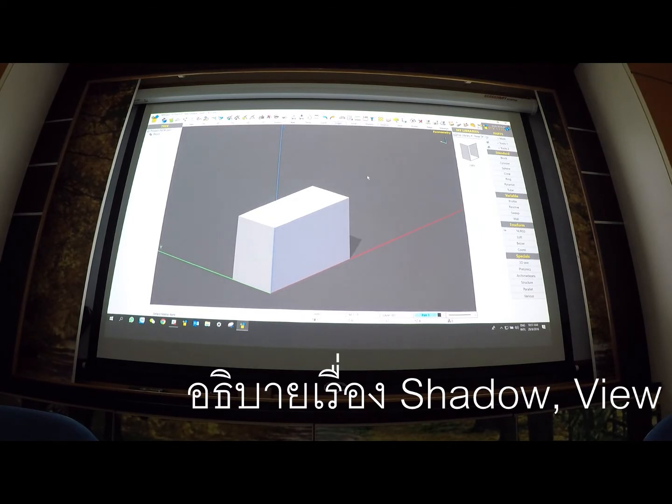Okay. Then you can see from here, is my block different from yours? Do you all have the blue line on the block? Okay. So if you want to turn it on, we have this function. To see the blue line, you just click on H. H plus is to turn on.